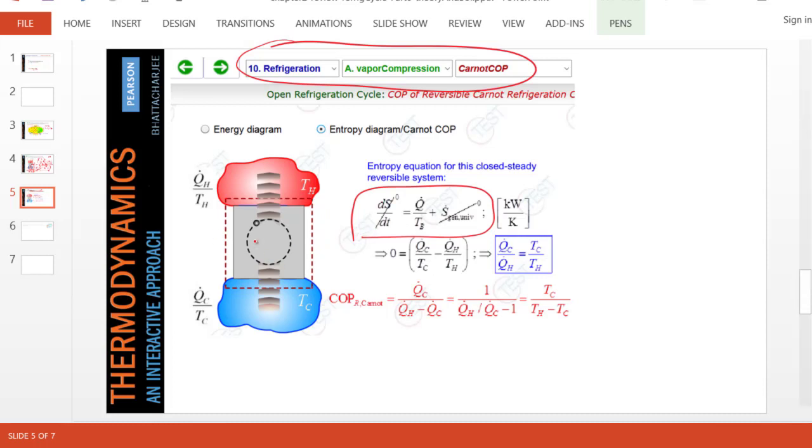And there are only two ways entropy can change. Because there is no mass coming in and going out, heat we know can bring entropy in. And how much entropy is heat bringing? The amount of heat crossing the boundary divided by the boundary temperature, which is Tc in this case. How much heat is going out, and how much entropy is now thrown out by heat? Again, the answer is the amount of heat going out divided by the temperature of the boundary, which is different.